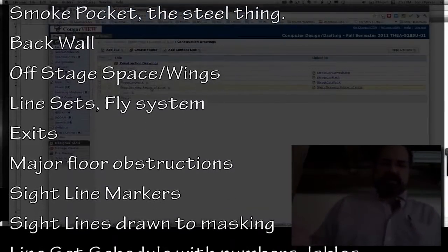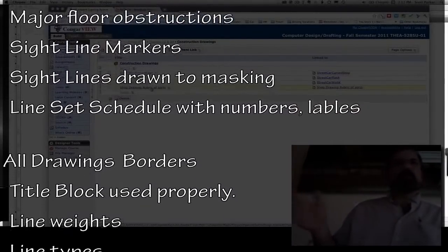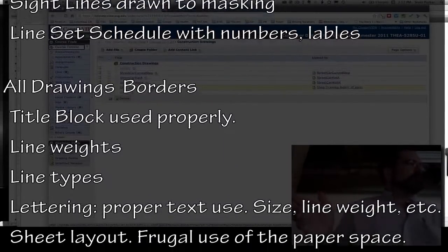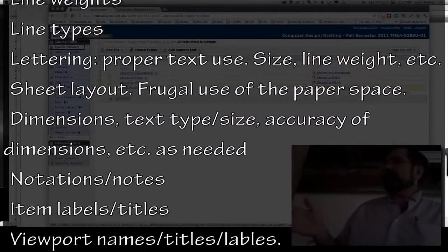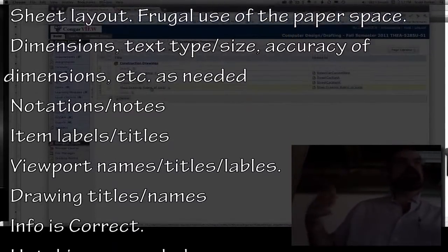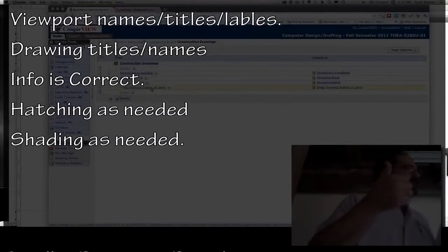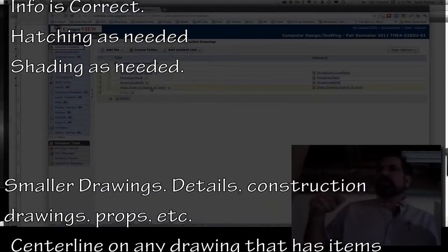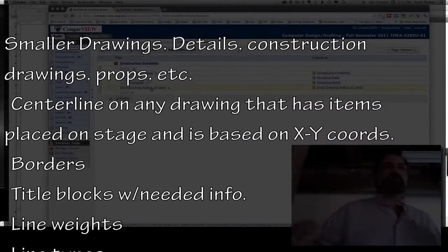Use of classes, use of layers, saved views, sheet layers, various tools. If you have one view and it's one object, I'm not worried about you having 27 different layers. If it's something that pertains to different layers, let's say you're using your base template file that we've created of your theater, and you'll notice that whenever I open an example file, usually I'm opening one of those template files, and then I just build upon it and I turn off all those additional layers.